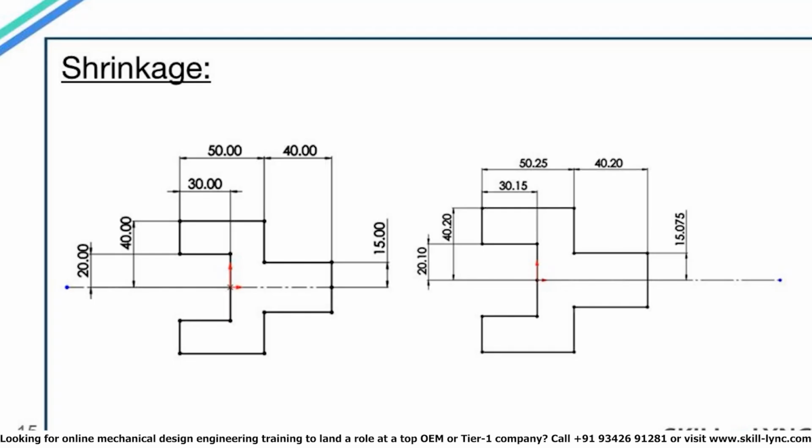If you want to confirm the values on the right, then you can convert the percentage value into fraction by dividing by 100 and then add the value of 1 to get the factor by which you need to increase the value. So for 0.5% shrinkage, you will divide 0.5 by 100 and you will get 0.005. Add 1 to it, the value becomes 1.005. So 1.005 is the scale factor, and all the values which you see on the right are the product of the original dimensions and 1.005.